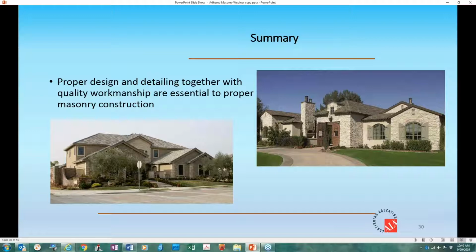All right. How far is lath held off the substrate for self-furring lath? 1/4 inch. Next question. Is there a height limit for thin veneer masonry without engineering? That's going to, again, be a local code issue based on your environment. So if you're in a high wind area, that may change versus being here where I live in Nashville. That's a local code question.